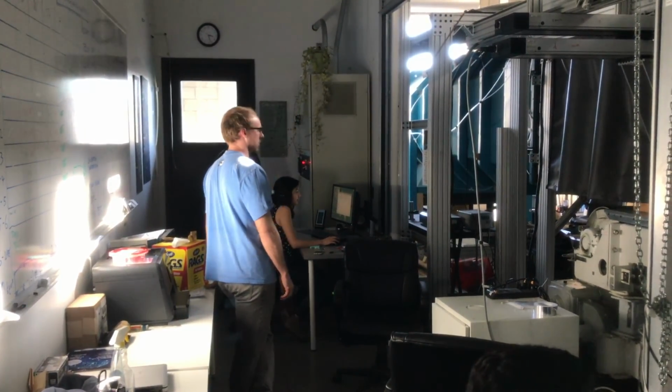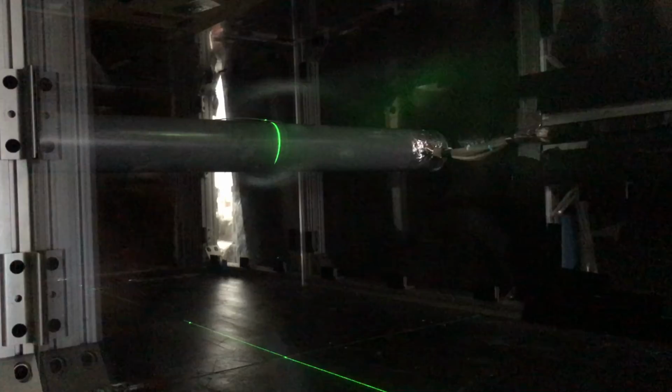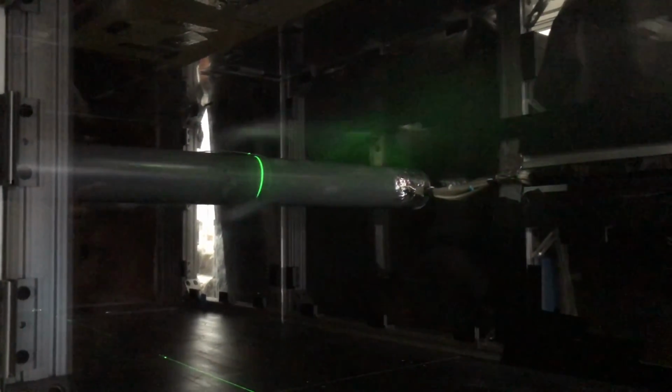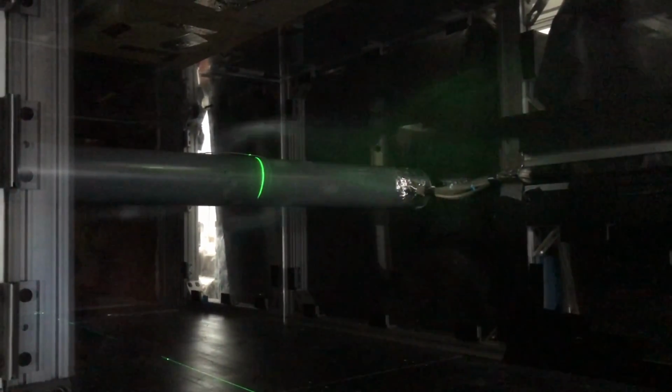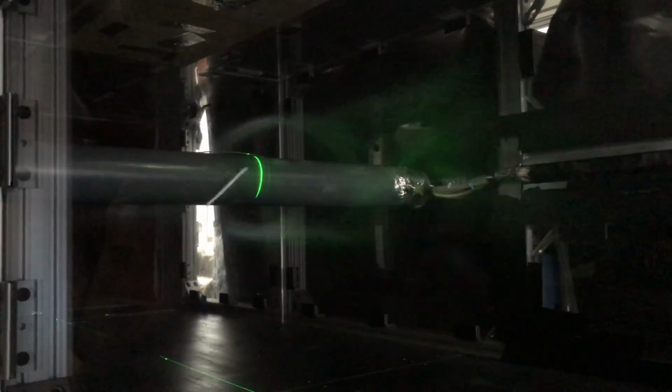In order to limit error as much as possible, the experiment methodology was followed very closely. A less significant error that affected the data was movement around the lab. Multiple times, people walking around the lab opened doors as well as walked in front of the inlet when the wind tunnel was on. During the first run with the sandpaper trip strip, the strip detached mid-test. The test had to be stopped due to this problem, and all the data relating to the sandpaper trip strip had to be retaken.